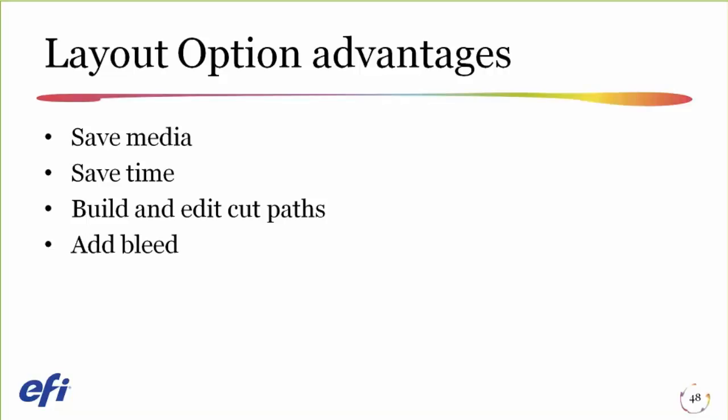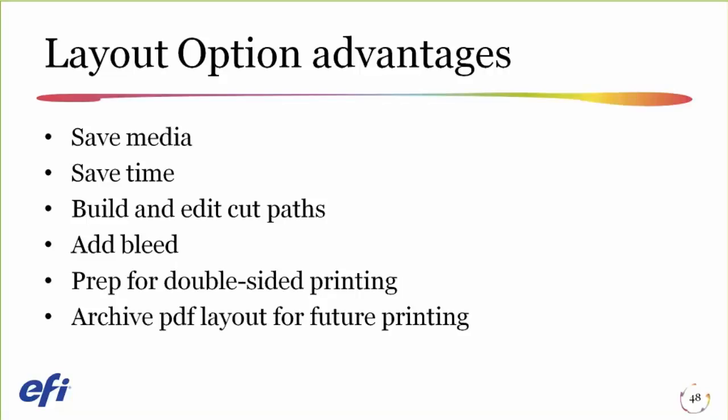We're able to build and edit the cut paths. We can add that bleed, which again helps enhance the final cut. We're not limited to the best original artwork to build these cut paths from. We can also prepare for double-sided printing and archive any of these complex PDF layouts for future printing. So as you can see, the advanced layout can really bring a lot of enhancements to your installation of FieryXF or Fiery ProServer and to your workflow in general.